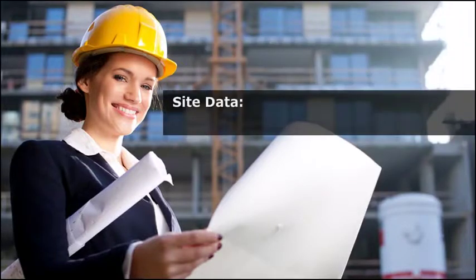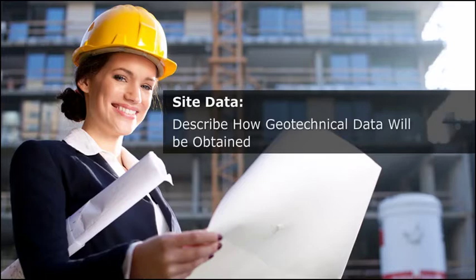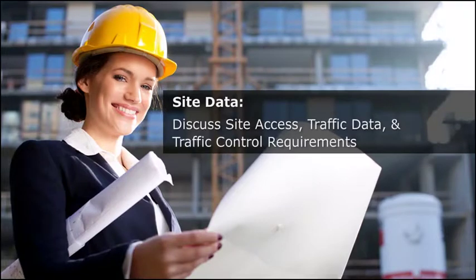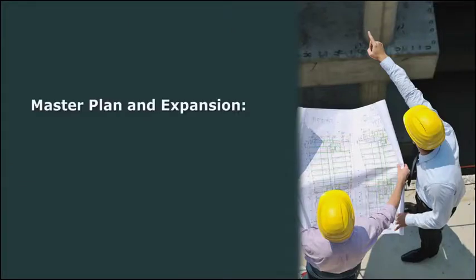5. Site data. Describe how boundary, topographical, and other survey data, including easements, will be obtained. Includes permanent and temporary construction easements. Describe how geotechnical data will be obtained. Describe how location and size of existing utilities will be determined. Describe any utilities that must be brought on site for a functioning project. Discuss zoning restrictions. Discuss site access, traffic data, and traffic control requirements, and discuss site drainage features and identify any investigation required.